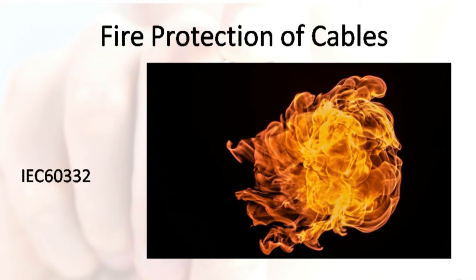With both types of cables, there are various fire retardant coatings available depending on the manufacturer that prevent fire propagation along the cable. I would also recommend looking at low flammability, zero halogen material options.